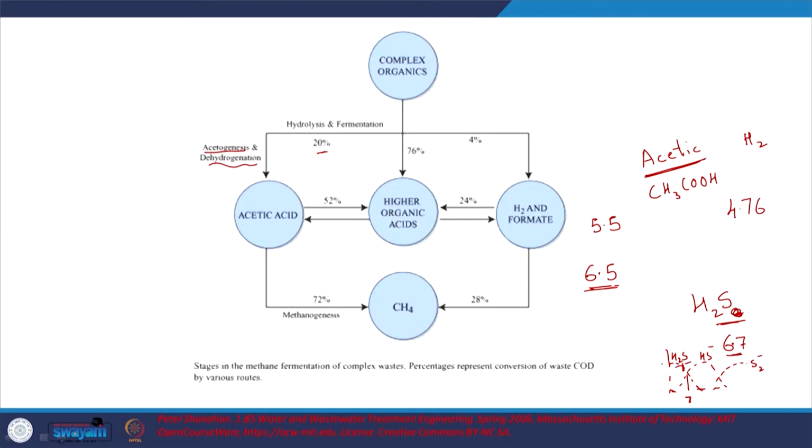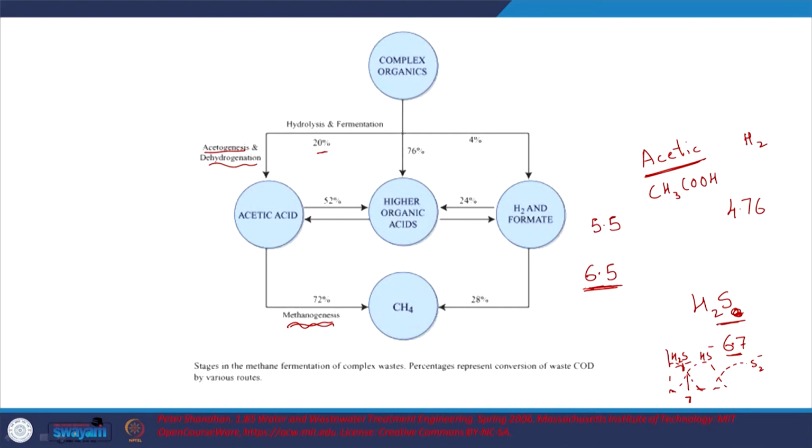So, here, similar to us, the microbes are very picky, right, and that is why the microorganisms, especially the ones that lead to methanogenesis, the methanogens, are called the prima donna, right. You need to really take great care of them. Any changes to their environment, and they will start nagging at you, right. So, these are the prima donnas, I guess, of this anaerobic digestion process, where the pH and also the toxicity of some of the relevant products, even at very low concentration, is important.